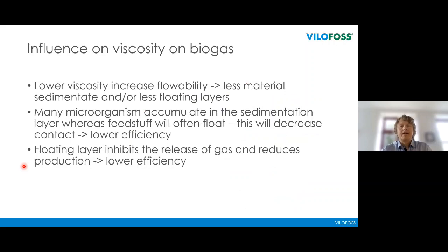It also affects the way the organisms work in all this material we have in the liquid, which is here in the slurry. So if we can lower the viscosity, we increase the flowability of all the material. We will have less material sedimenting at the bottom, and less floating in the layer, which is often the feed component you will have on the very top.